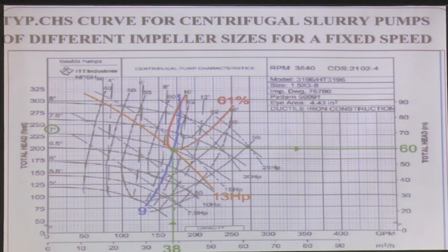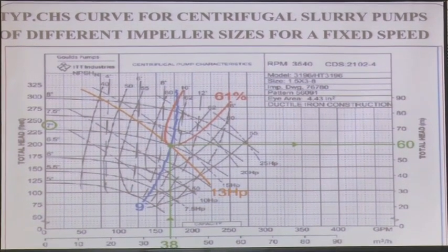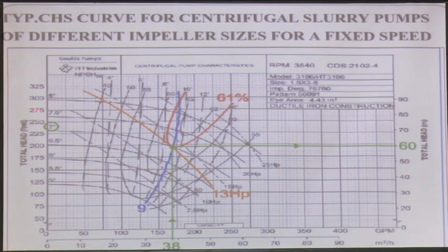Now, this is the typical one. Total head is this. So, total head and total Q, the point is placed over here. Now, while placing the point, it may so happen that it falls within or on the pump characteristic curve. It may so happen that it lands in between the 2, any point where there is no speed mentioned.